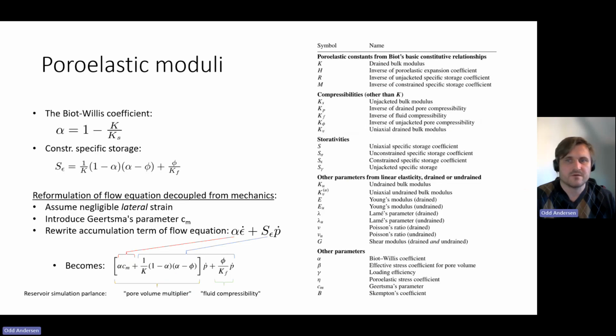So I just mentioned that there are many possible choices for poroelastic constants in order to specify the system completely. Here on the right is a list of some that you may encounter in the wild. Their definitions are based on different physical assumptions and the nature of what they represent. However, since there are only 4 degrees of freedom to specify the basic poroelastic system, it is clear that these are all related. The theoretical relationships between each of them can, however, be quite complex and lead to annoying extra calculations to convert between them to get the ones that you are interested in.